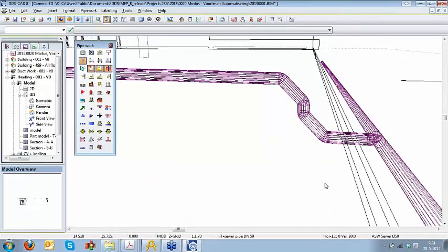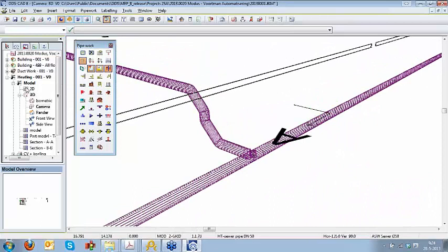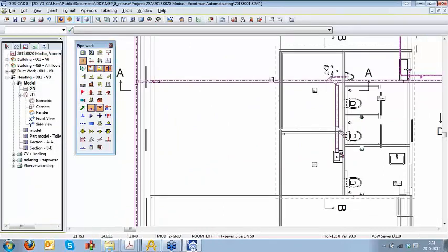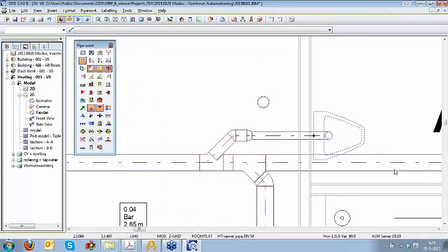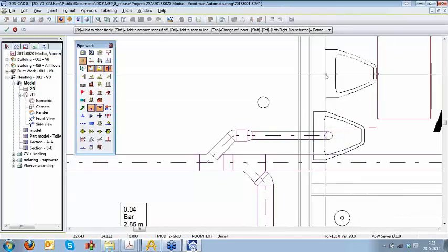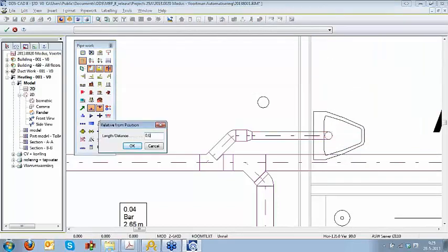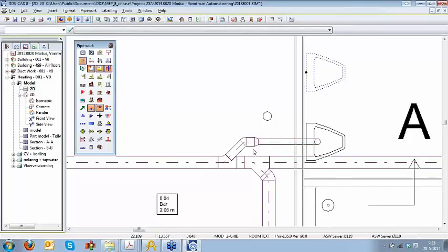So it's not up to me to say, okay, this can be made, but what is the most optimum situation in this case? Furthermore, when applying from our sewer system on the right side, I already connected a urinal. When I take another option of the urinal by copying the object, by pasting the object on my mouse cursor, and I would like to have it 60 centimeters as an offset in positive Y direction. So this is my second urinal, and I can continue from this bend making the connection.